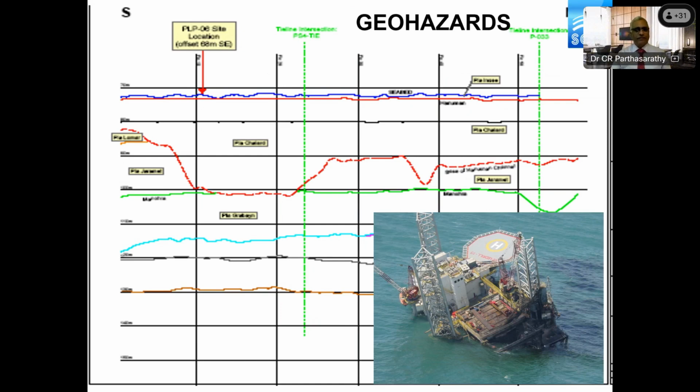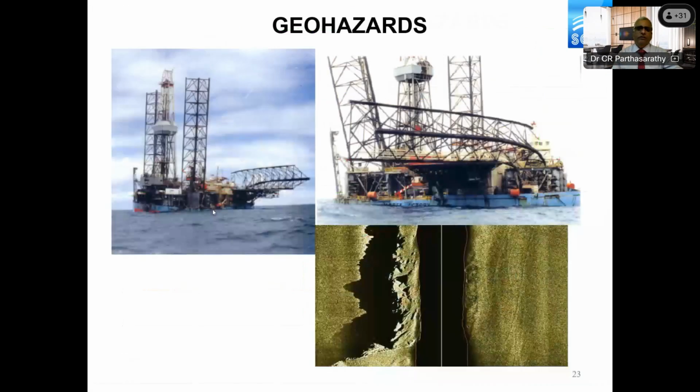So then you identify these channel features, then it's too late. You have to avoid them, because the borehole is already done. We have seen that in many cases, and therefore we urge the clients to make thorough planning, where you send the geophysical survey first, get the data, then you go to the drawing board, do the desktop analysis, then you perform the geotechnical investigation, so it will have meaningful results.